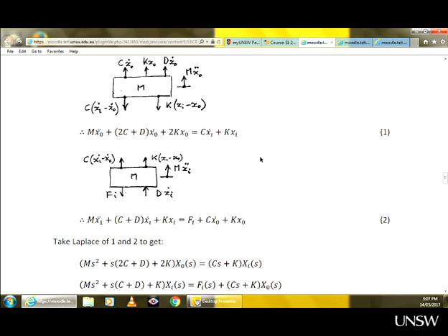I don't understand what this means, DC. DC gain, or steady state gain. You get it because on the previous stage we had a definition. When you write your transfer function in a non-dimensional form, so instead of k you have 1, that means here you have m over k, but that's irrelevant. Here you have 1 over k. 1 over k is the DC gain. This is the steady state gain.